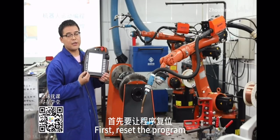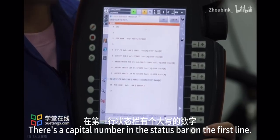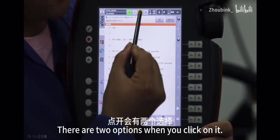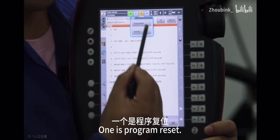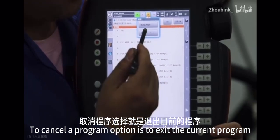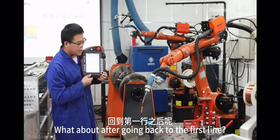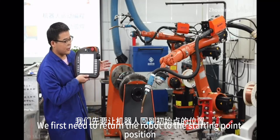What about testing? First, reset the program. Where there's a capital letter R in the status bar, there are two options when you click on it. One is to cancel the program selection. One is program reset. To cancel a program selection is to exit the current program. Reset is to return the cursor to the first line. What about after going back to the first line? We need to return the robot to the starting point position.